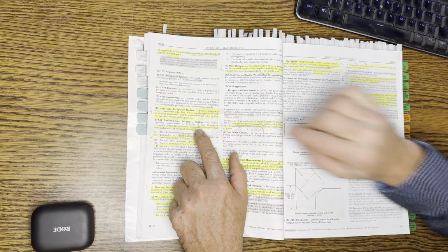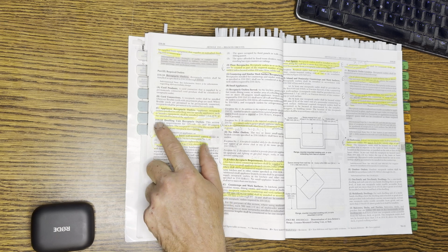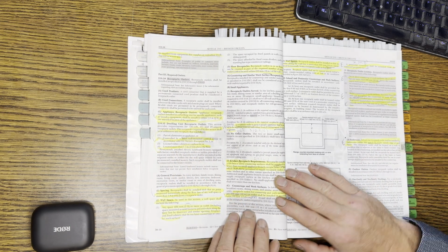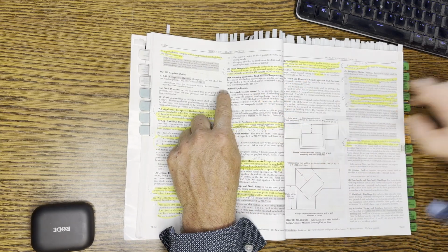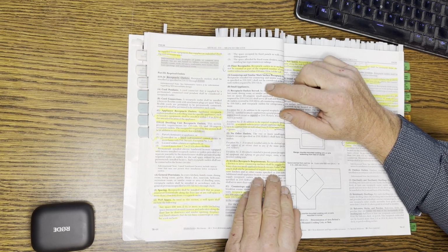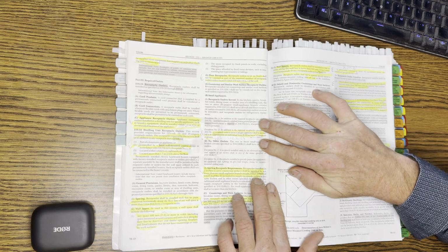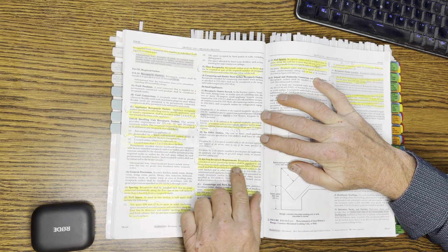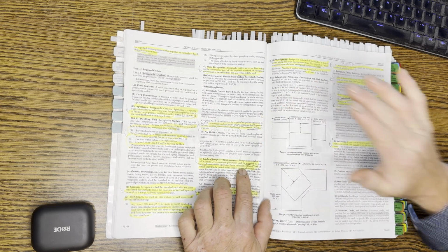Okay, dwelling unit receptacle outlets. And it's B3. So if you look at 210.52, let's go to subsection B. And let's see, where are we at here? There's A, B. There it is right there. B3. So let's go to B3. Kitchen receptacle requirements. So receptacles installed in a kitchen to serve countertop surfaces shall be supplied by not fewer than 2 appliance branch circuits. Done. There's your answer.